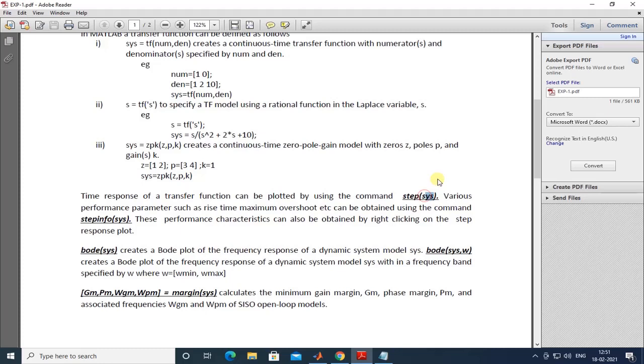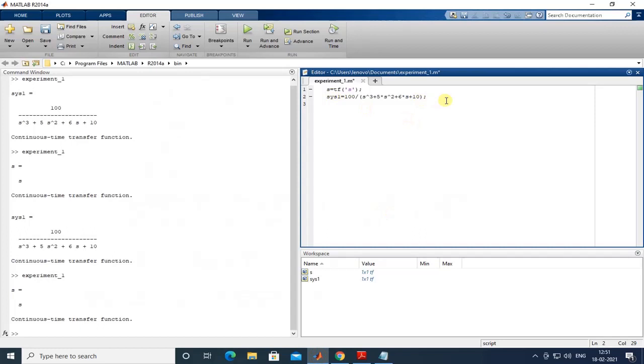So this name is arbitrary. In braces, the transfer function name will be arbitrary. Whatever transfer function you choose, just apply that name over here, and it will be done. So let's try these two. Let's try step. Now our variable name or transfer function name is system1. Now let's run it.